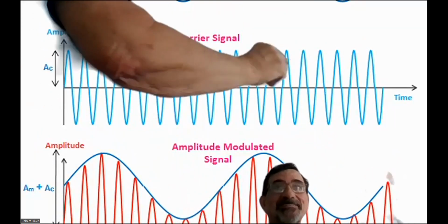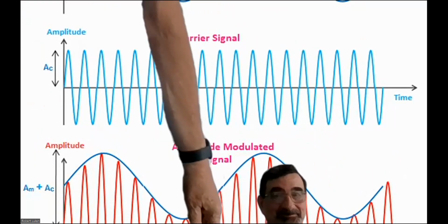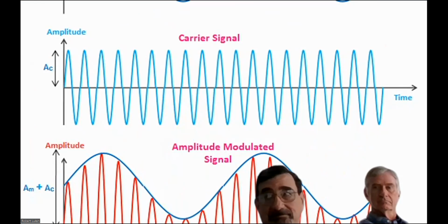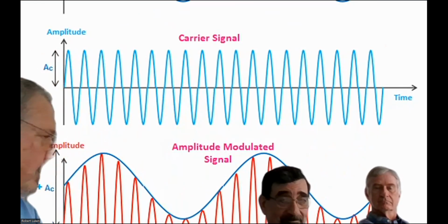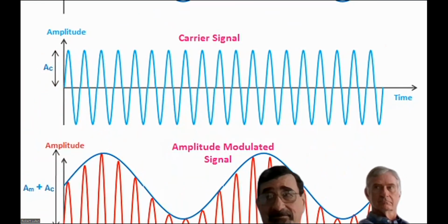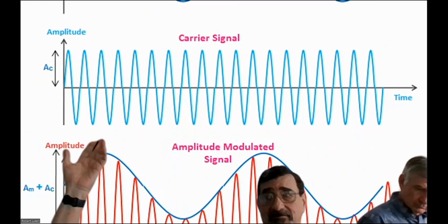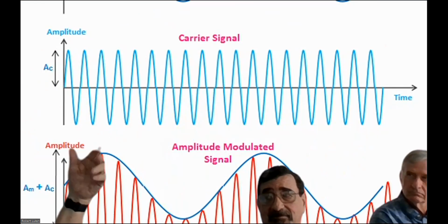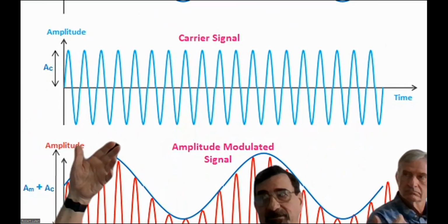It's a magnetic field, right? But it's copper, and that piece of copper tube is a coil, one turn shorted together. So if we take a magnetic field and run it across a coil, you get voltage in a magnetic field. It causes a current to flow.